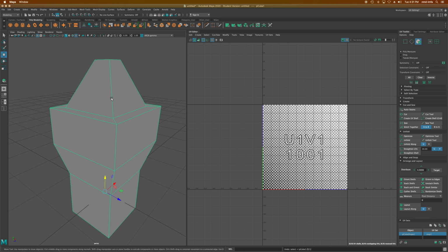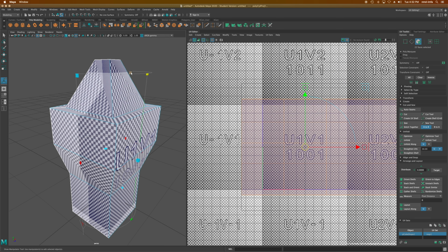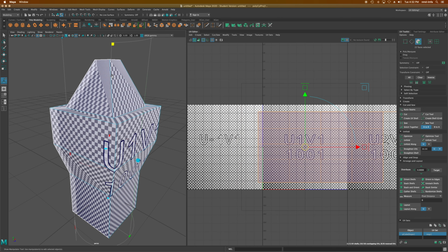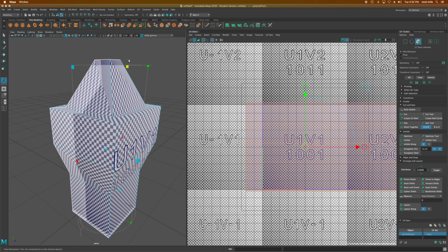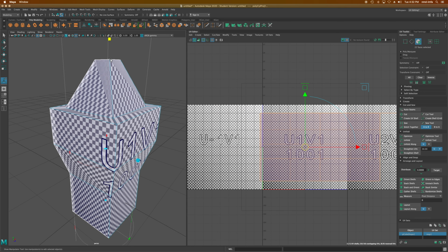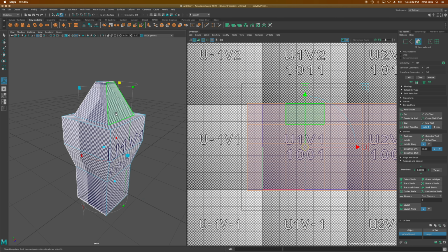There's different ones for different types of structures. There's cylindrical, there's planar, there's spherical. So obviously a spherical one's going to work really well on a sphere, a cylindrical one's going to work well on a cylinder. If I bring cylindrical in here, I actually get like a manipulation cage that allows me here on the left to interface and scale things. So if I did have a cylindrical object, very quickly I can do my UV mapping and make it fit. You see I don't have the same kind of cuts over there that the automatic did. I have this cylindrical cage that I'm working with.